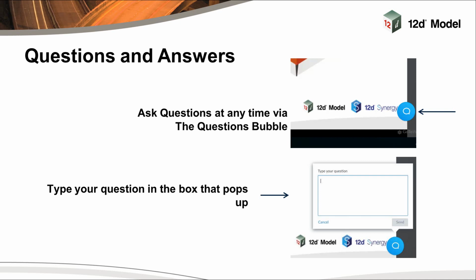Can you change the orientation of the plan in plan view? For the long section plot, no. When you're using the plan plotting within the PPF file, the orientation is automatic, to best line up left to right along the screen for the long section. But if you want total control over that, you could do as I suggested and insert your own plan frame on that page and orientate it yourself, rather than have the PPF orientate it automatically for you.